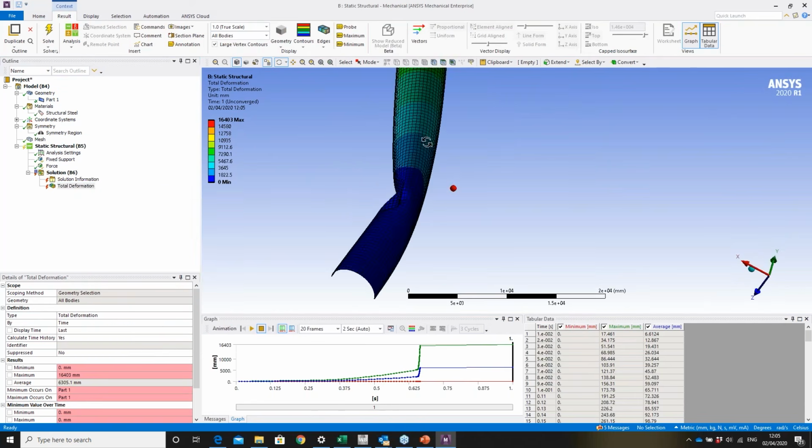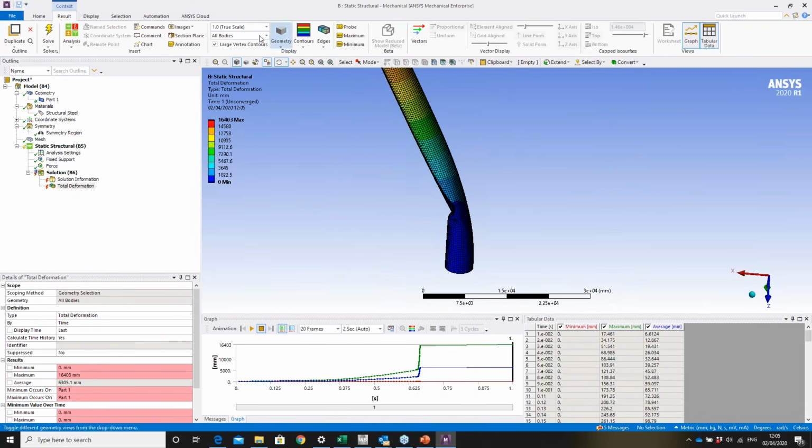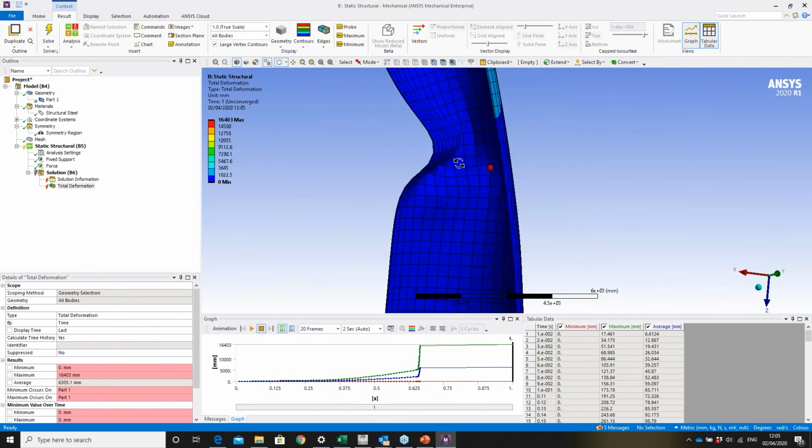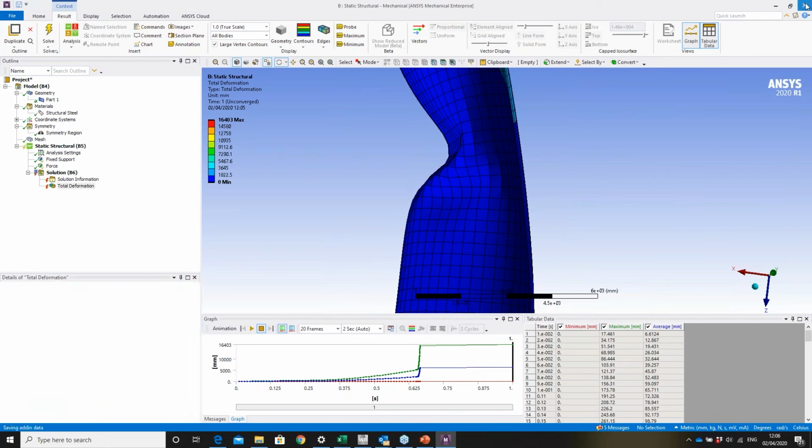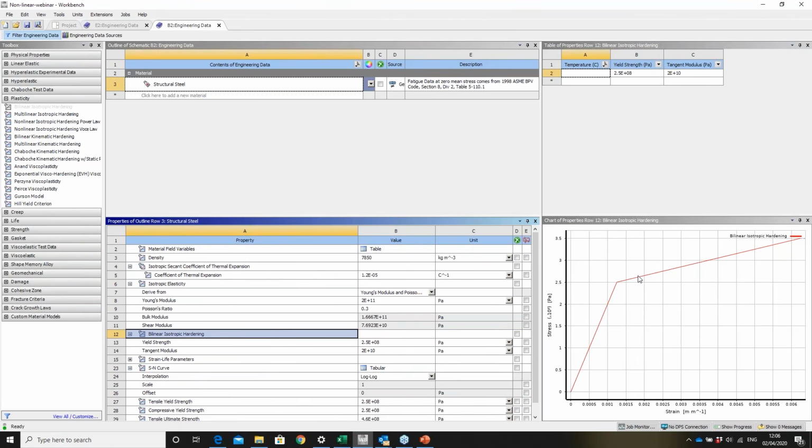can see there. So here we can see, we've got it on true scale. We can see how it's starting to buckle and collapse down here. And if I started this solution and gone again, it would go on and it would solve to the full load, and we'll get an almost 90 degrees bend in this structure. So that's non-linear buckling, and it's a specific type of analysis.